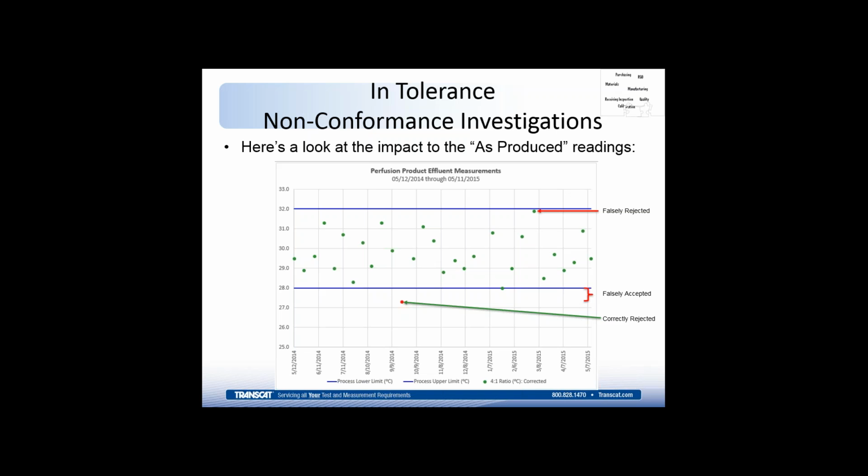Now, in all of these scenarios, if the temperature instrument was calibrated and found to be out of tolerance, that would have normally triggered an out of tolerance evaluation, and you would have gone through this process anyway. The point here is to find the quality blind spots, where you don't see an out of tolerance on the calibration of the instrument, therefore you don't do an evaluation. You had a lower process accuracy ratio of the instrument to the product tolerances, and you should have been aware enough to know to go back and evaluate that.